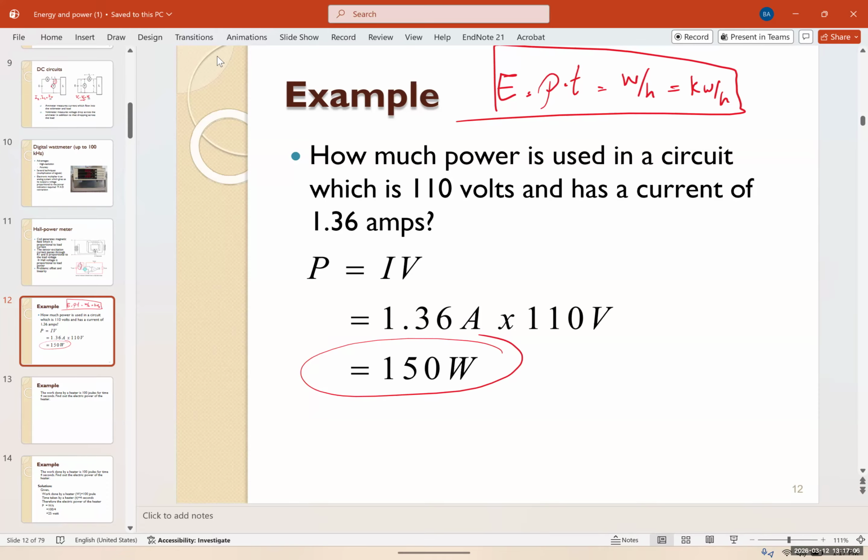So the nominal power of a wind turbine could be 3 megawatt, but it almost never works at its peak output. You have to have ideal conditions to produce 3 megawatt for an hour. Usually it's around 60, 70, 80% of that. So you're producing 2.42 megawatts for an hour. And again, it depends on the wind situation and a lot of different factors.